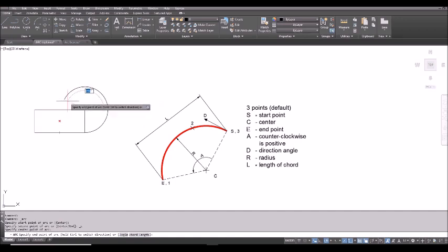The end point actually is just for defining the included angle. You see, if I click an end point in the middle of a rectangle or at the end, you can see it still gives me the same thing. And the arc end point will not touch the point I'm clicking. So the end point here is to define the size of the arc, not exactly the end point of an arc. Okay, get the idea? For example, I click here, you can see the end point I click is the lower left corner, but the arc ends in the middle there.